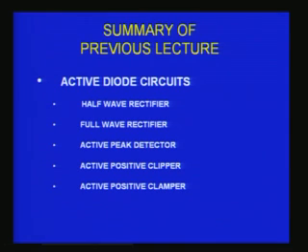This ideal diode was used in different applications, like making a half wave rectifier, then how a full wave rectifier can be implemented using such an op amp along with a diode to make an ideal diode. Then we also saw some variations of these, like the peak detector, the active positive clipper and clamping circuits, which are very useful in different wave shaping circuits.